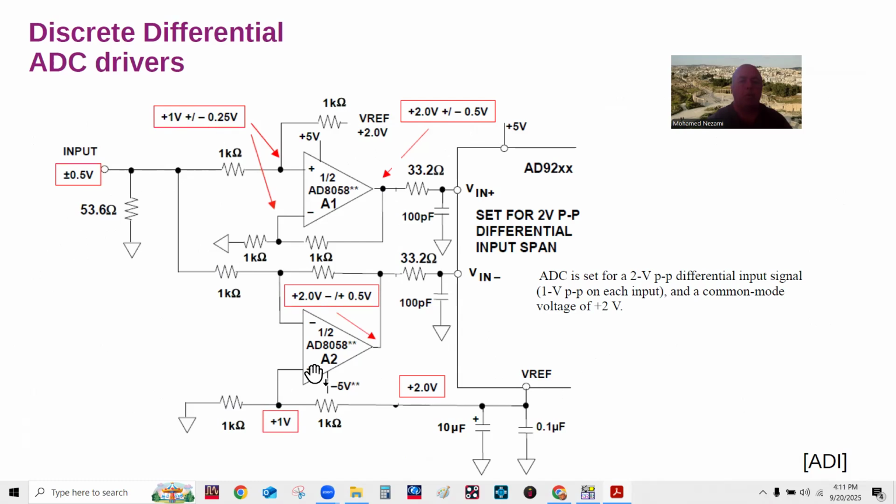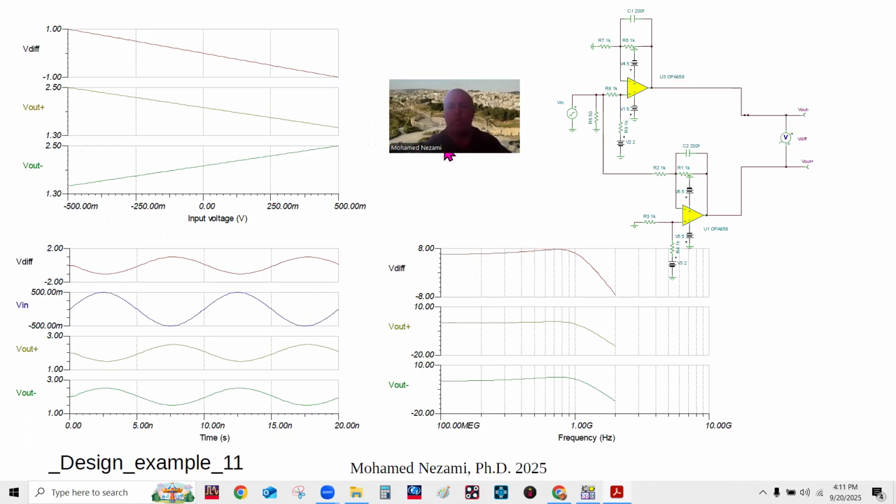So we're taking 1 volt with two equal resistors. That gives a gain of 2 for the non-inverting port, which means it's 2 volts, okay? And the same thing we do in here. We bring in the 2 volts directly on the non-inverting one, and that basically comes out here. So now we need a gain of 2 in here and a gain of 2 in here, okay? And that should work.